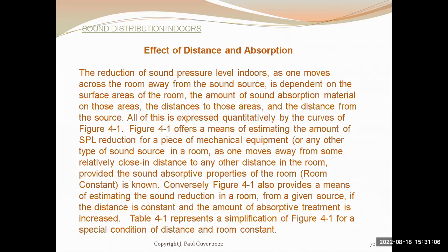But in the source room, the sound reductions normally in building design due to distance and absorption are very small, and you don't pay any attention to them because, among other things, they're just kind of a little freebie that you get. You get a little bit more sound reduction than you would get strictly from the barrier.